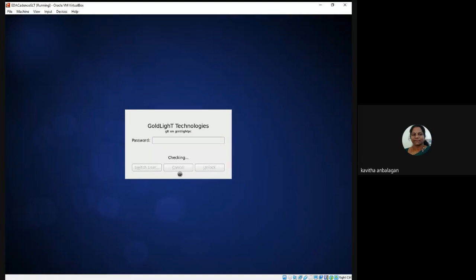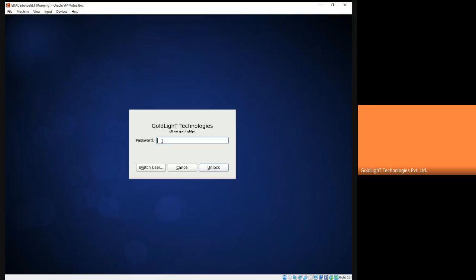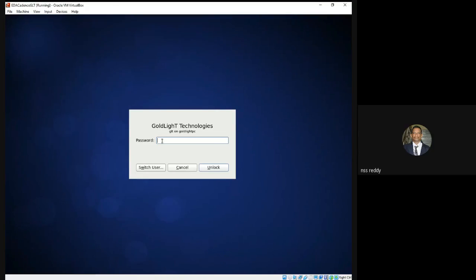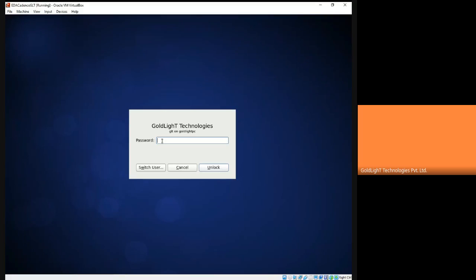Okay, sir. Which one will give a better result, using Verilog code or designing a circuit? Actually, if you are going for a very big design like a Fourier transformation or compression techniques and all, then you should use Verilog code only. There is no other way. Circuit level implementation is practically not possible.